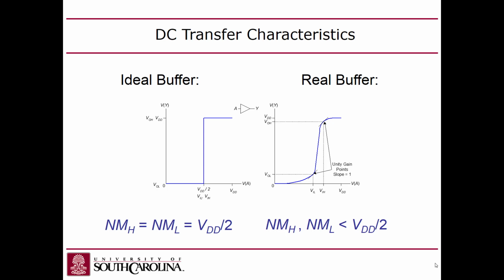So you can have an input that is supposed to be a logic 0, but it's kind of like 300 millivolts because of some noise, right? Some noise got added, so we're not quite down at ground. It's a logical 0. We want to be at ground ideally, but because some noise was added to the transmission line, to the wire, we're really up at around 300 millivolts.